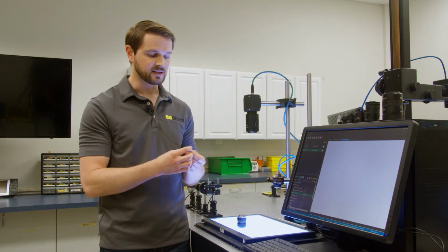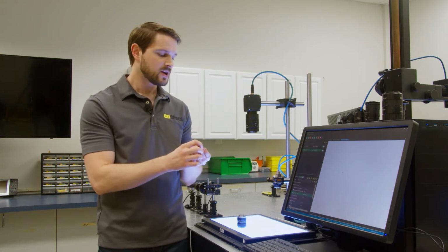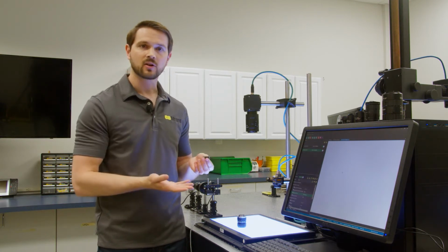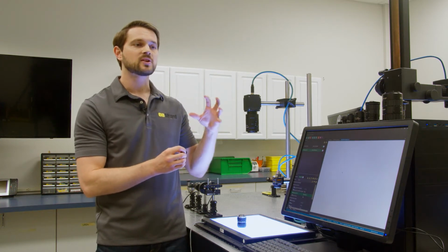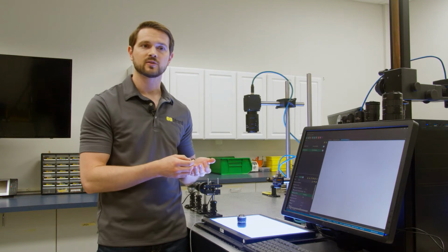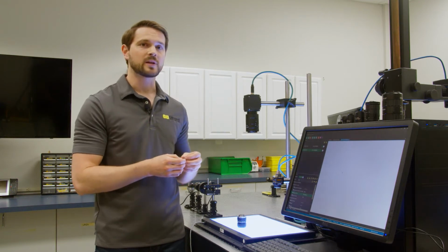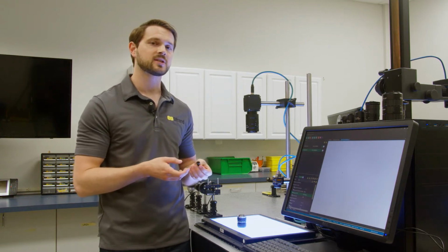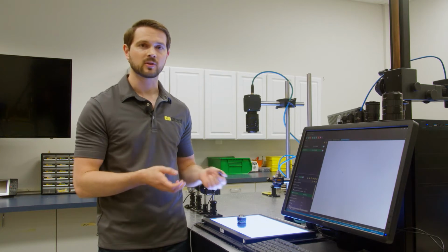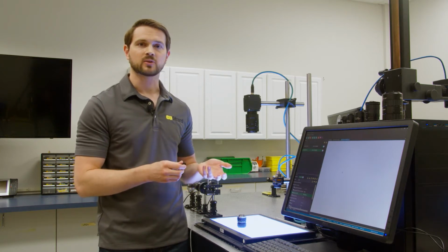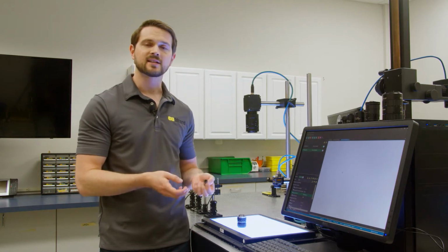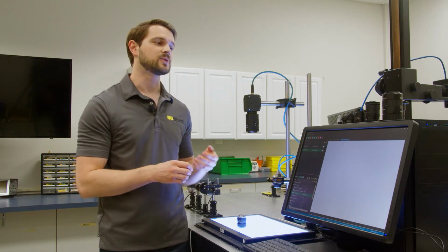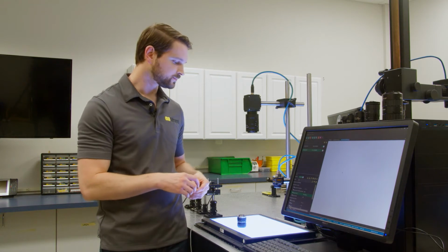Because lenses are obviously round, right? Which means that they output images that are also round or circular. And that means that we need to make sure that the sensor we're designing the lens for will fit inside what we call our image circle. Now, most of the time you won't hear the term image circle outside of the optics realm, really, but you can see it sometimes, especially if you're using line scan sensors or something like this. You might be able to spec a lens with respect to its image circle.